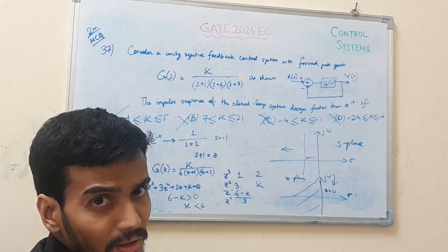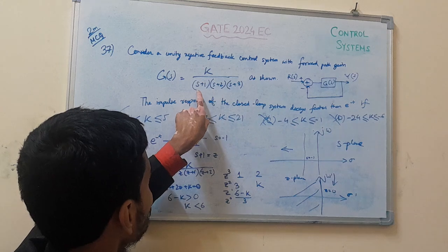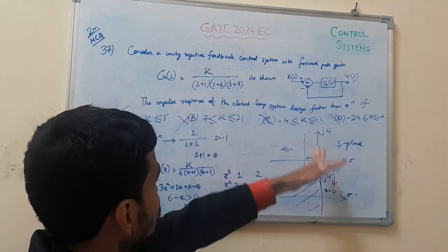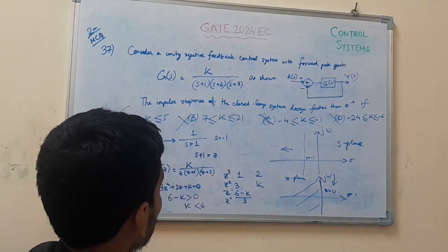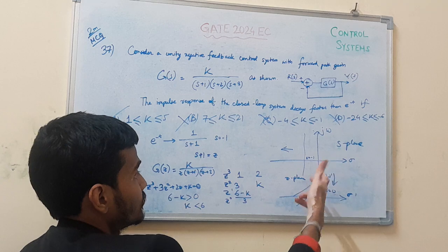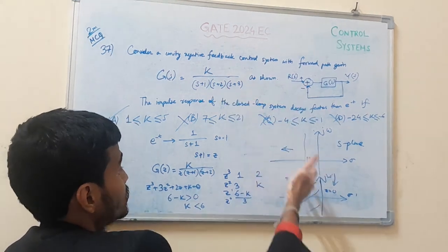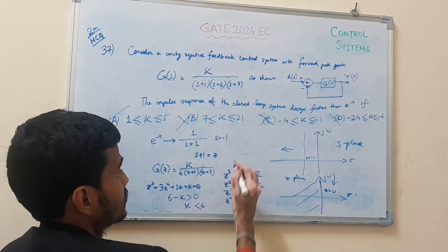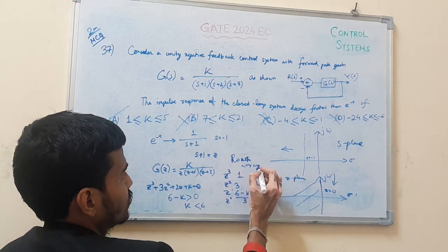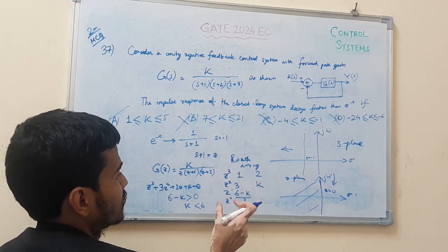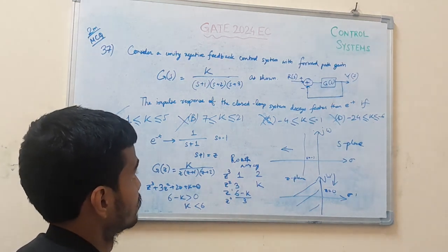As explained, this is a slightly unconventional approach, hope it is clear. We first convert the s variable to z by shifting the j omega axis, such that it falls in the conventional method of finding poles in the left half. The condition on k for the poles to be in the left half comes from Routh's theory. Next, we follow the conventional steps to find the range of values of k for which the system is stable,